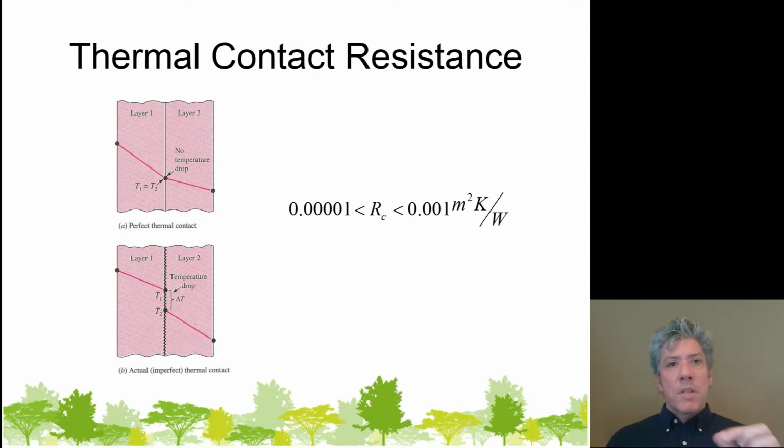You might say, well, that doesn't make any sense because you've got to somehow get power to the LED, and the aluminum would just short it out. And you're right, but the way they overcame that is the aluminum bars themselves were coated in a paint, and then the traces for conducting electricity were laid down on top of that. Any vias, which are holes that have electrical conduct going through, turns out they drill and then they coat those as well with this insulating paint.